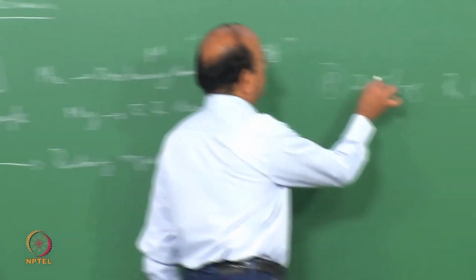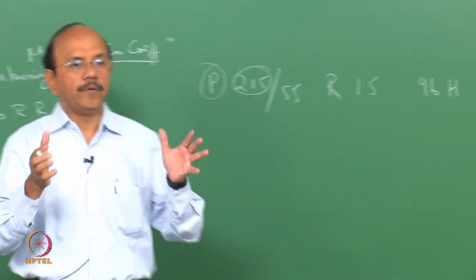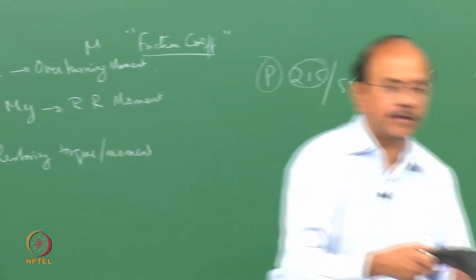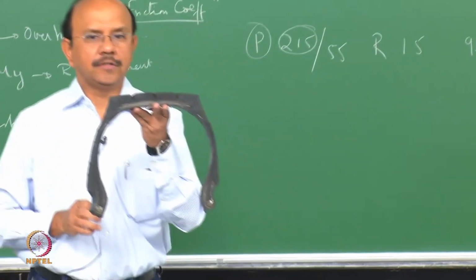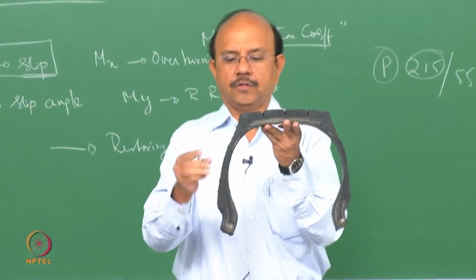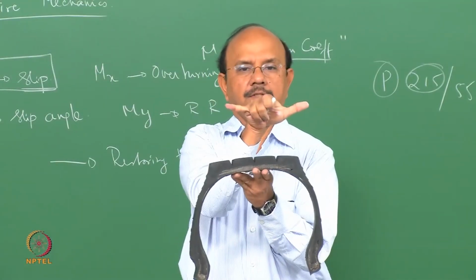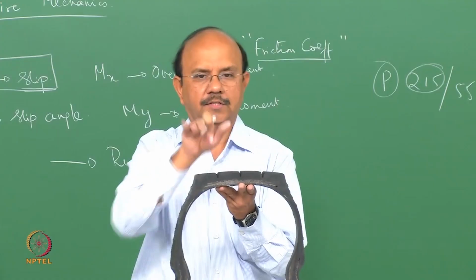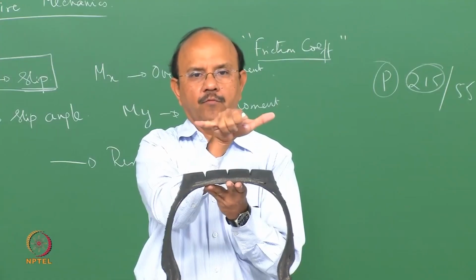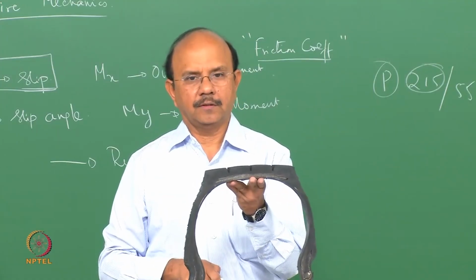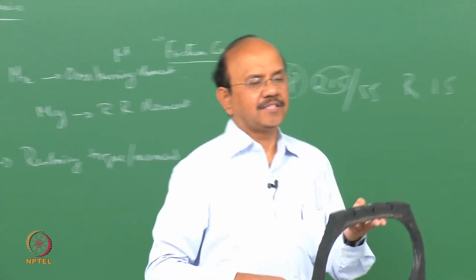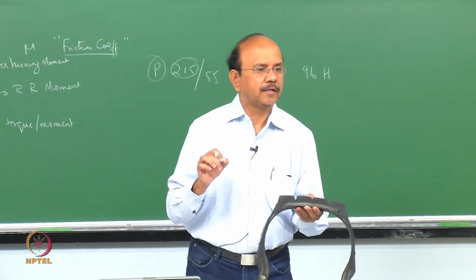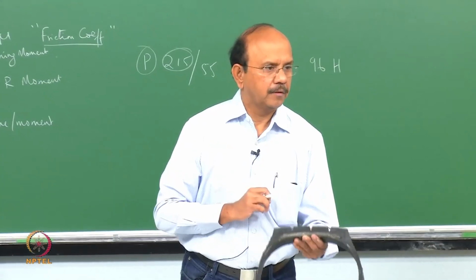215 is the biggest section width of an unloaded tire. Let's look at a section of the tire. So this distance, the maximum width, is called the section width. So you specify that section width. Note that the section width is specified in millimeters.